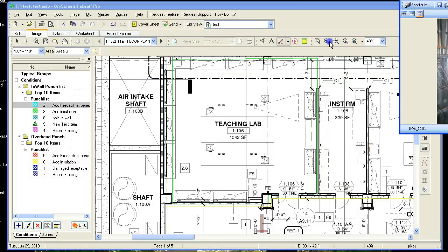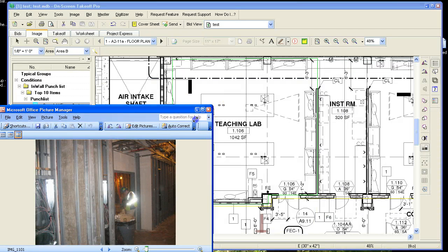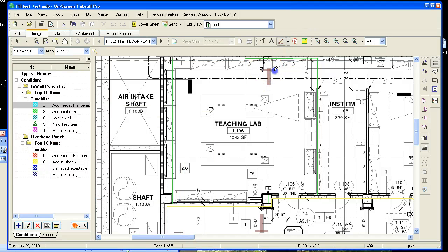And I take another picture, it comes in down here, where do I want to put it? Okay, now this one is right up there. So we're tying all that back to an actual location in these drawings. Furthermore, we could have an intelligence where on this floor plan it knows it's at a certain level in the Revit model, or the Navisworks model, whatever it may be. So that picture is shown at two different places. We can turn on the layer to show in the PDF floor plans, and also in that BIM model. I see it being extremely valuable.